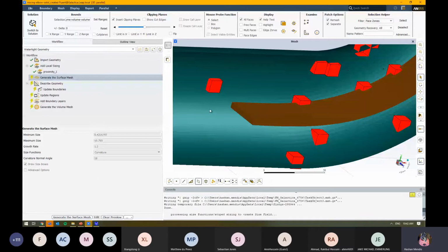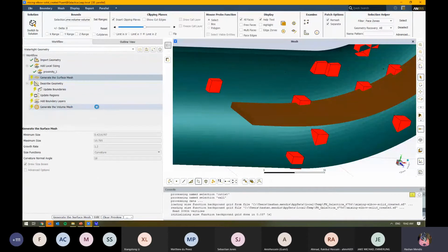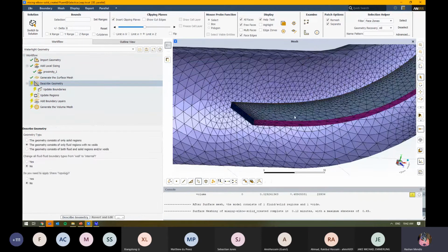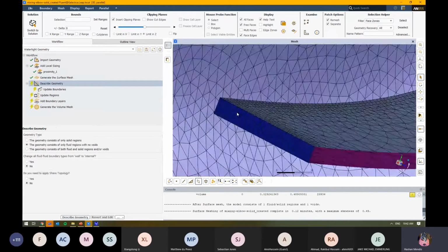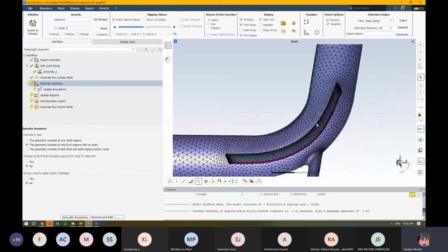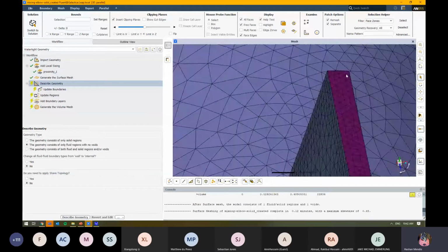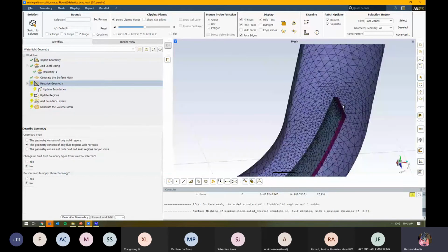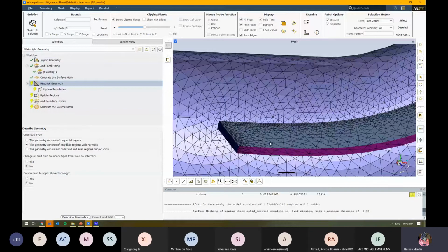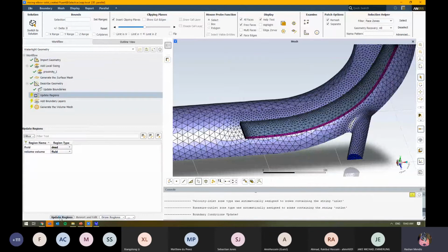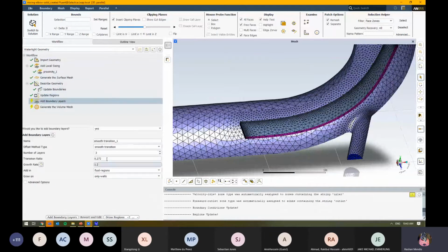So we'll just generate the mesh. Again, we can go to the very bottom and just generate, we'll go through everything, but I like to go through and make sure everything is exactly what we expected. This allows me again to go in and manually check what I've just done, make sure it's correct. I haven't put the wrong numbers or values in. You'll notice just where we've got an edge, between the two edges is where we've got some sizing. All over these faces, not much is really happening. It's just growing out to be as large as it needs to. So all this is fine. So that's all described. We can update the geometry there. Those regions all look good.